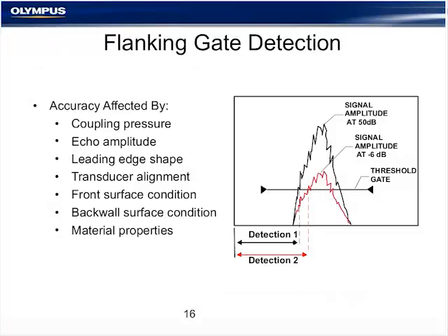Now, the detection algorithm, I mentioned before, Olympus has a very specific way of measuring repeatably and accurately the back wall reflection from a dual transducer. And there are actually two factors involved when we look at the comparison between this automatic thickness gauge detection algorithm and something more standard on a flaw detector. The first has to do with flank detection or edge detection on a flaw detector.